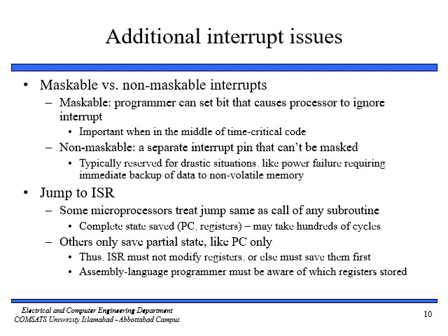Once you are just saving the value of the program counter, your interrupt service routine cannot modify the registers, or else must save them first. So in the previous case we were saving the registers so that we can modify them, but in this second case we are only saving the PC, so we cannot modify registers. If you have to do so, you need to save them first.